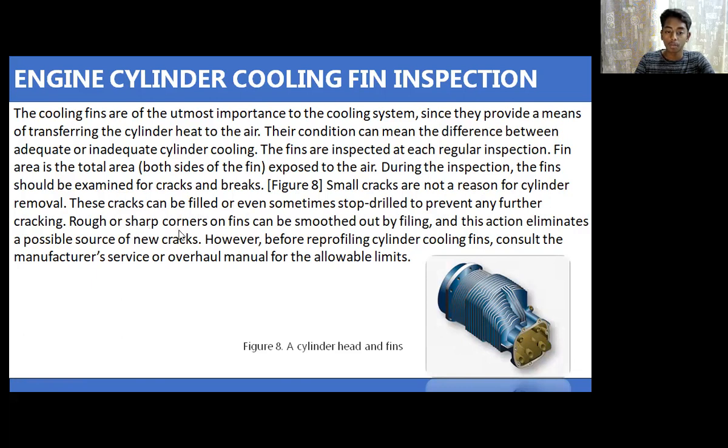Rough or sharp corners on fins can be smoothed by reprofiling, and this action eliminates a possible source of new cracks. However, before reprofiling cylinder cooling fins, consult the manufacturer's service and overhaul manual for the allowable limits. This is how the overall maintenance and inspection of the engine cylinder cooling is done.